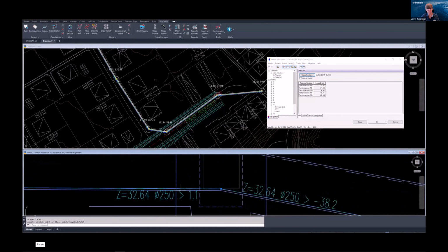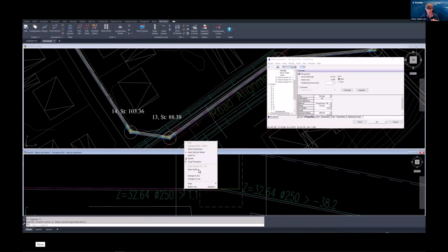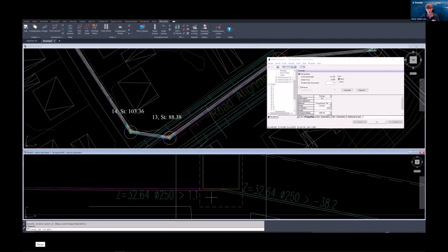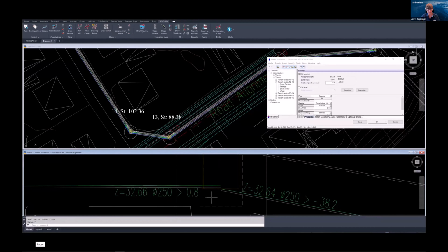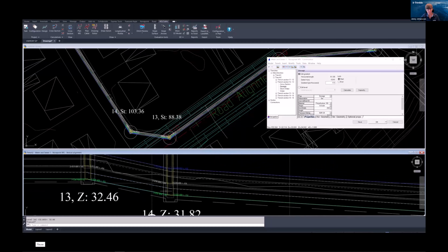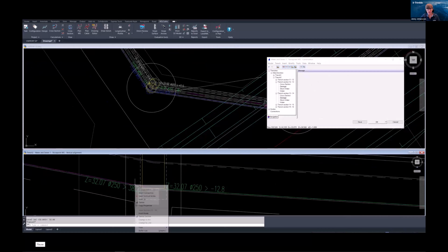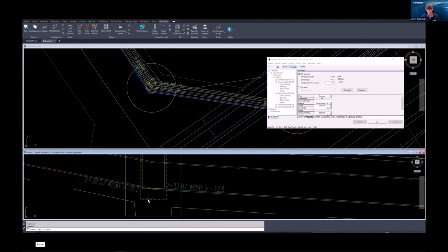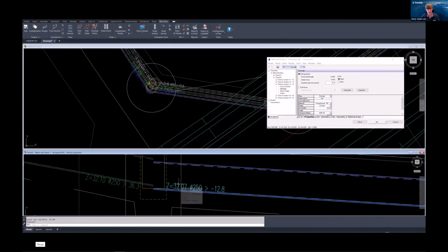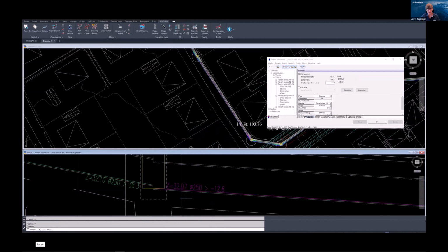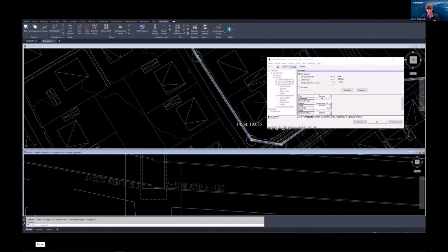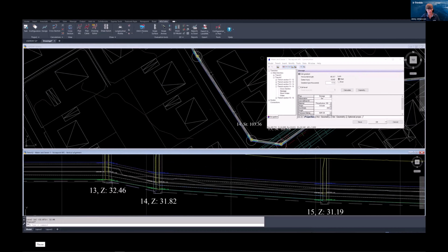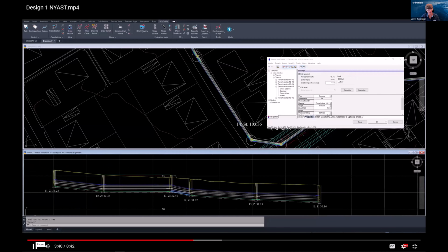To change the pipe set value, just right-click the pipe and type in a new desired value for the pipe. And as we see here now, we have 2 centimeters difference between incoming and outgoing pipe. And now I am going to change set values here for this manhole as well. Incoming pipe will be given a set value of 32.10 and outgoing will be given a value 32.8. And also here we have 2 centimeters of difference between them.